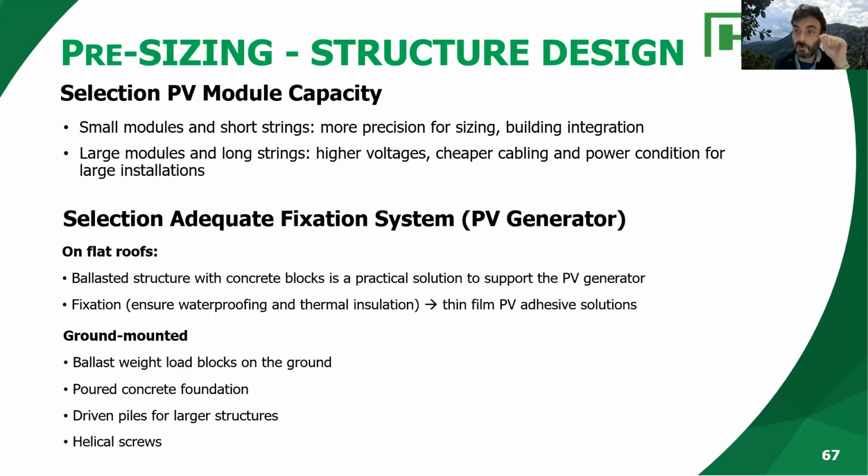No need for bolts or drilling, etc. Elements on the roof could be a problem. Also the weight load, especially in weather conditions like what you had last night, strong winds and rains. We need to put ballast loads to fix the structure so that it doesn't fly away, right?